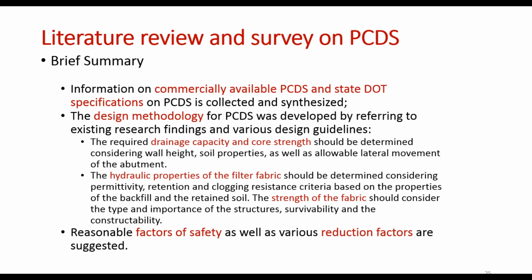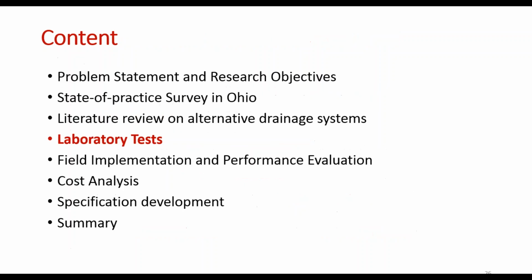So we think this is much more important than under drains and slope drains. So we suggest that we increase the requirements for the fabric in terms of the strength. And a reasonable factor of safety as well as reduction factors are also suggested to help us come up with some design values.